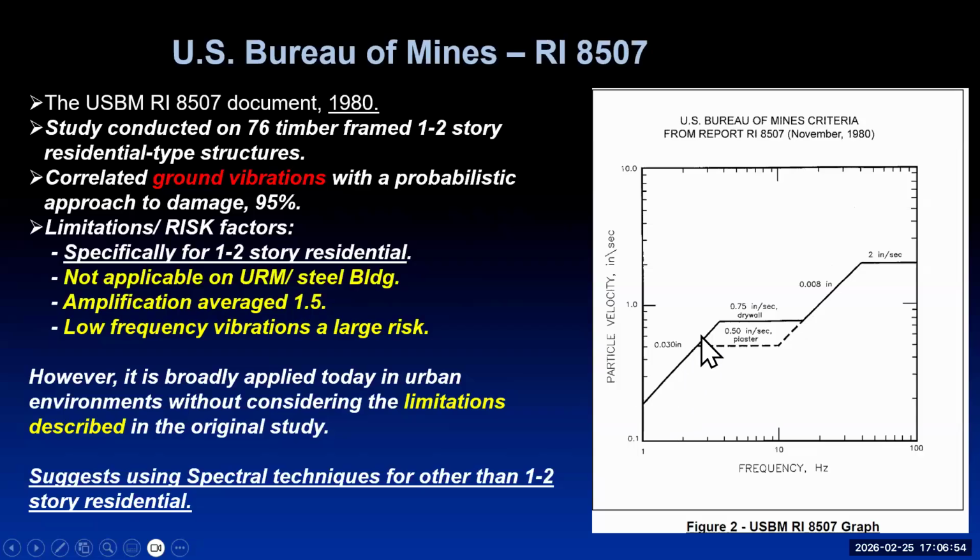But the point of this, it's not directly related to Dr. Geary's three-part curve, but it is a three-part curve, and it's based on displacement as a function of frequency. And then they also put it into peak particle velocity, which at the end of the day is really a derivative of a displacement measurement. So the lower the frequency, the greater the displacements are going to be.